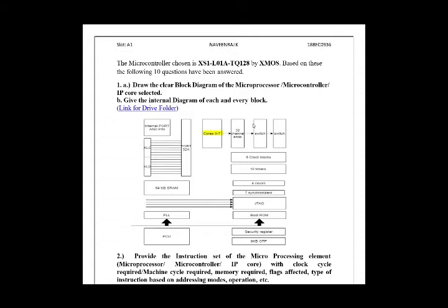Suppose a port is enabled, it overrules ports with higher widths that share the same pins. The pins on the wider port that are not shared remain available for use when the narrower port is enabled. So the sizes of the ports will vary, wider port, smaller port, and they might share the same pin. The pin selection depends on the data transfer rates.